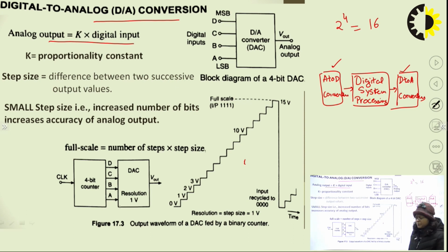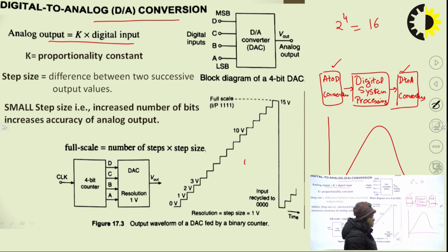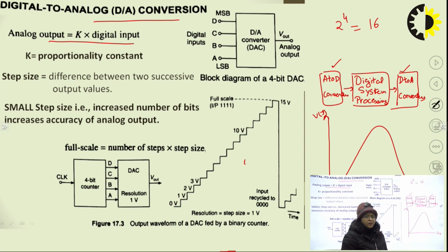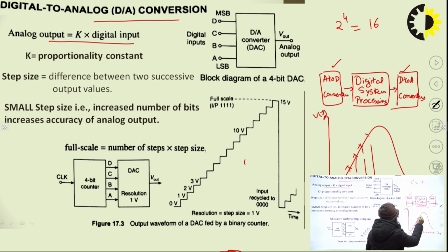We will consider an example of how to convert an analog signal to digital. Consider this as an analog signal which is continuous in time as well as amplitude. So first we will convert this signal into discrete, that is discontinuous form. For that, first of all, we break this signal on the time axis, that is make it discrete on the time axis. For this purpose, we take a discrete number of samples, a process called sampling, and remove all other values.